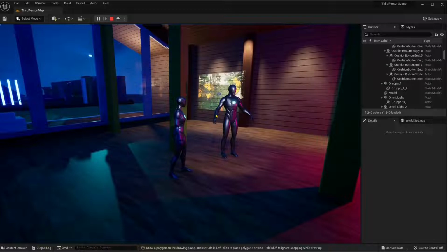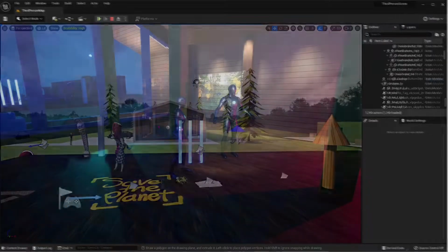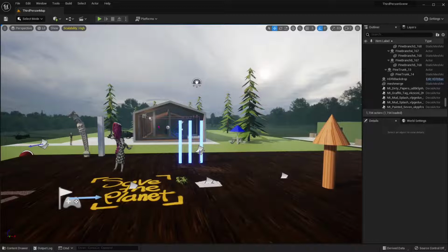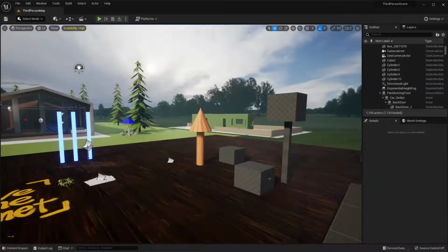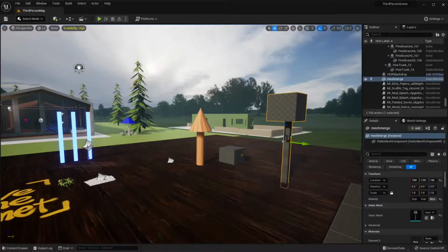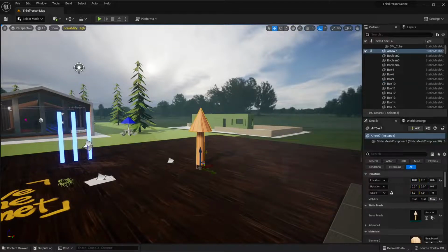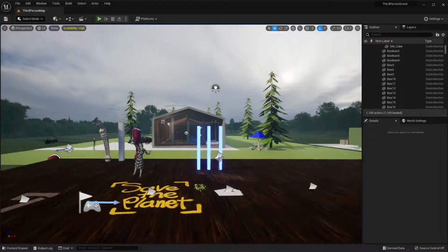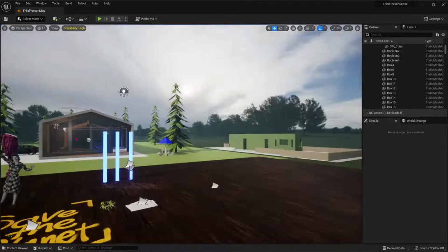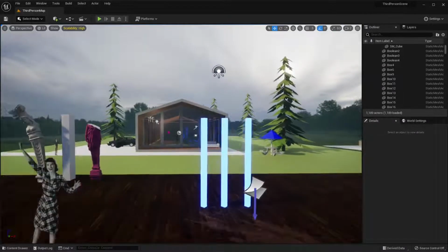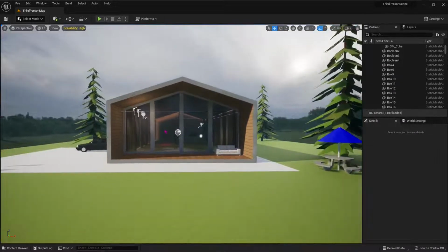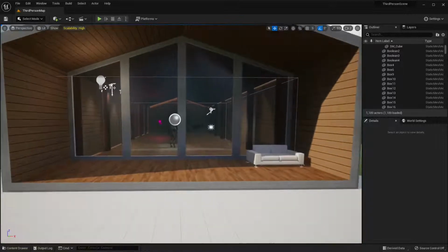We're going to see some render settings, how we can use cameras, how we can use the depth of field, and also other settings and effects that we can use with the cameras or with the post-production. Now I'm going to delete some of these assets here that I don't need anymore. Also, you can see I'm using an HDRI, so we're going to see how we can set up an HDRI system, so we can do image-based lighting or IBL.